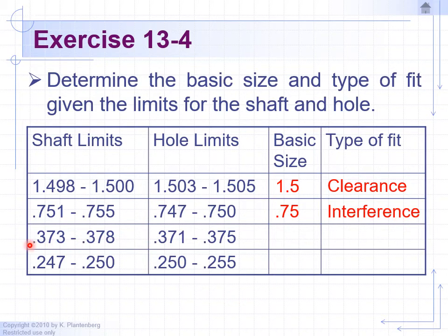Okay, obviously for the next one, we're looking at 3/8 or 0.375 for our fraction. That's what we're aiming for. Okay, so if you look at the shaft, 0.373 up to 0.378, and the hole, 0.371 up to 0.375.